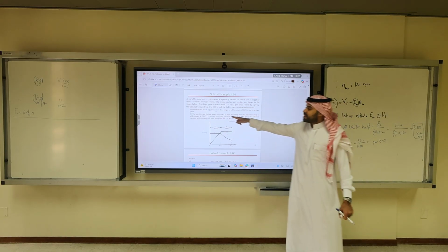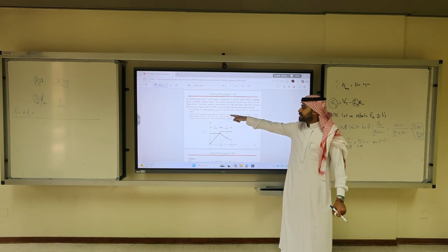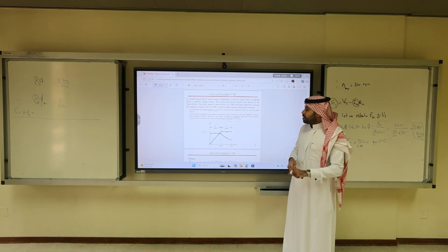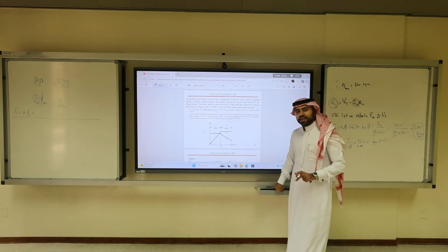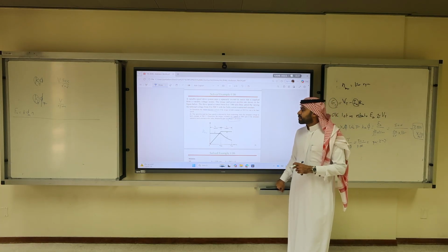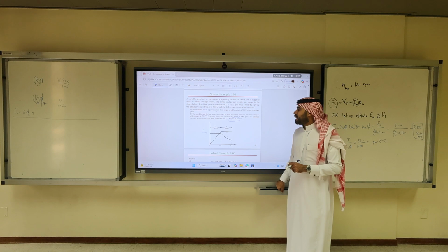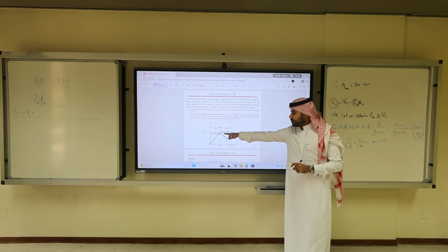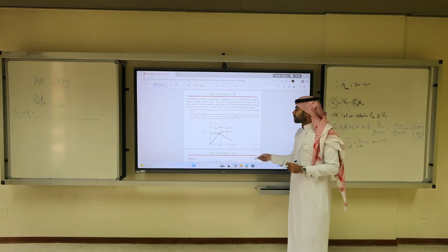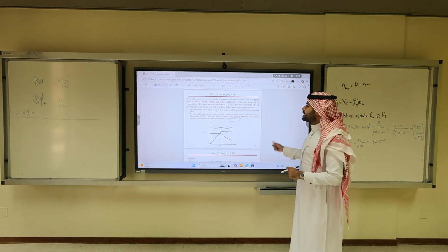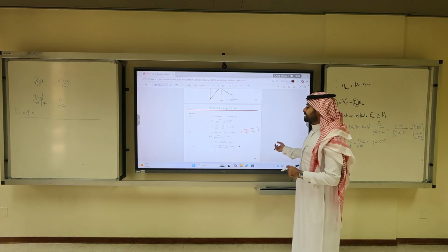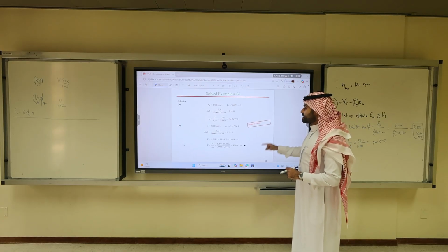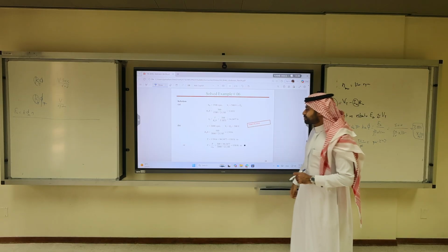Part B, the speed beyond the base speed is obtained by field weakening while the armature voltage is held constant, so Ea is assumed to be constant. Find the torque available at speed 3000 RPM. So the torque will be smaller based on the curve, if the armature current is held constant at the value obtained. So Ia is now fixed. Clearly here we use the same equations.